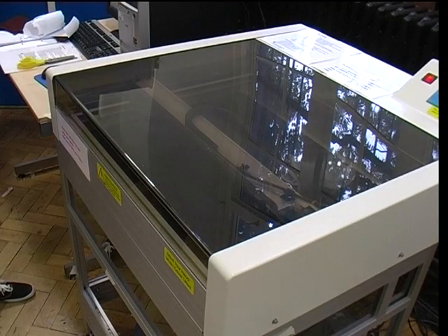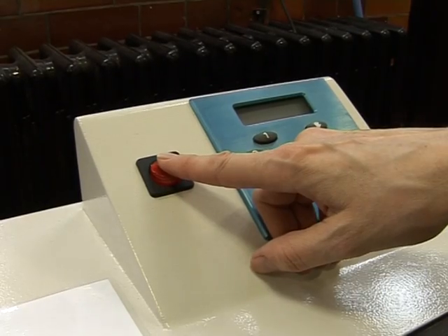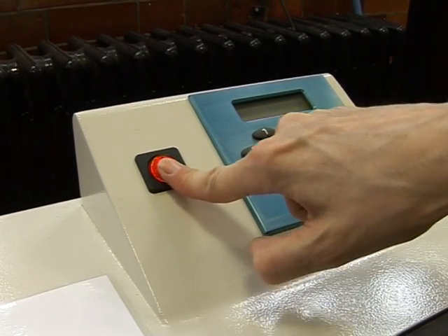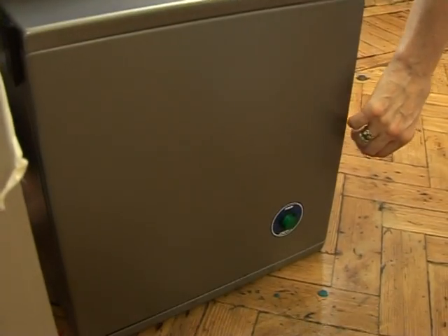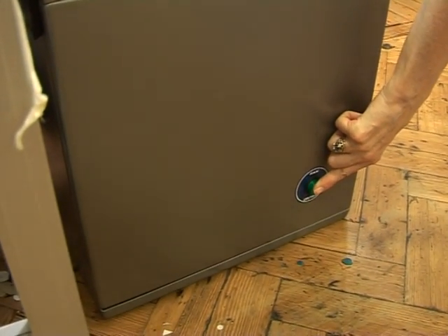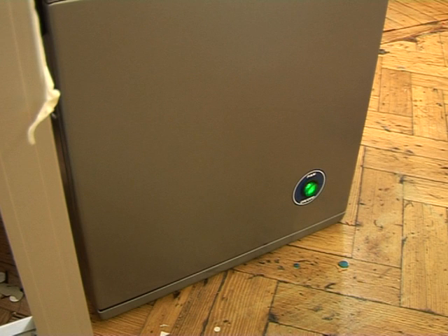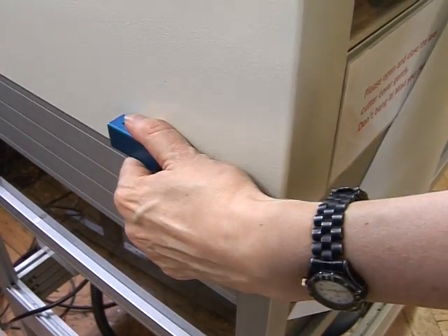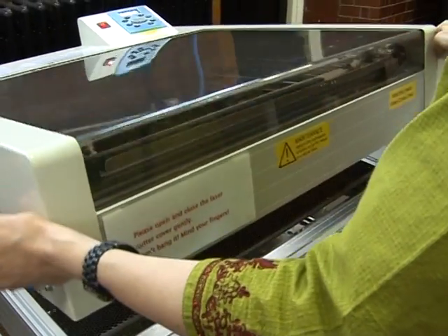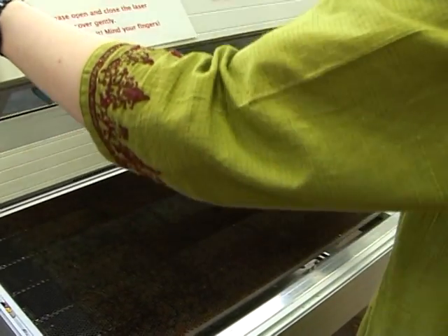Turn the laser cutter on. The red button on the panel will light up. Make sure the fans are on. At the right of the laser cutter, on the floor, is the extractor fan. Make sure the green button on the right illuminates the green light. Push the arrow indicated button forward and lift the laser cover gently.